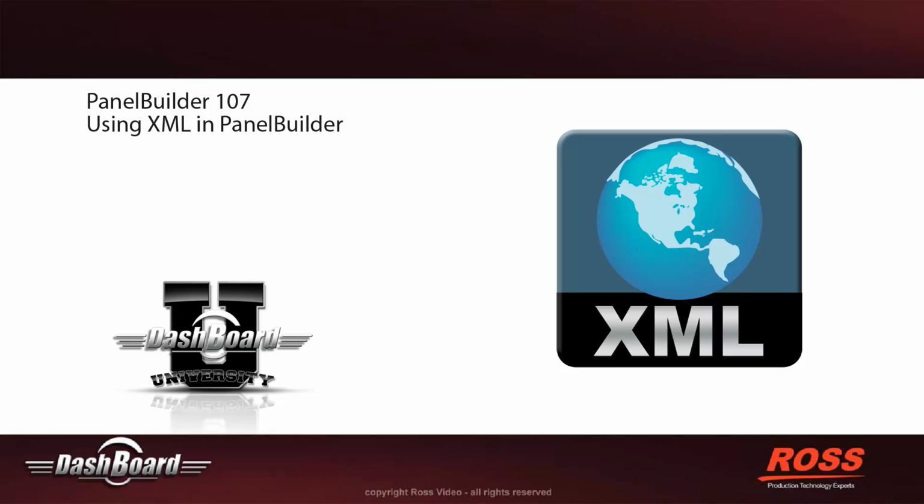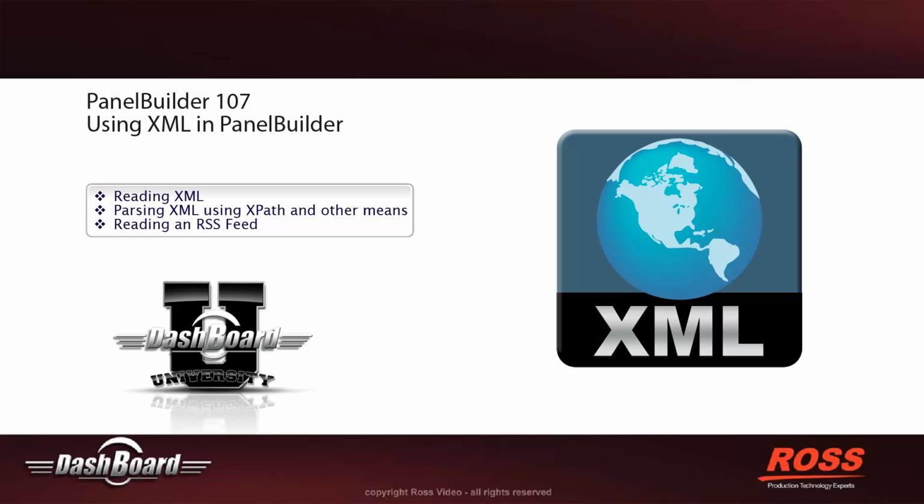In this movie, we'll look at using XML in Panel Builder. We'll show how to read an XML file in, and then parse it using a couple of different methods, one using XPath and the other using getTagsByName. I'll also cover how to access web-hosted XML using Ross Video's RSS feed as an example.